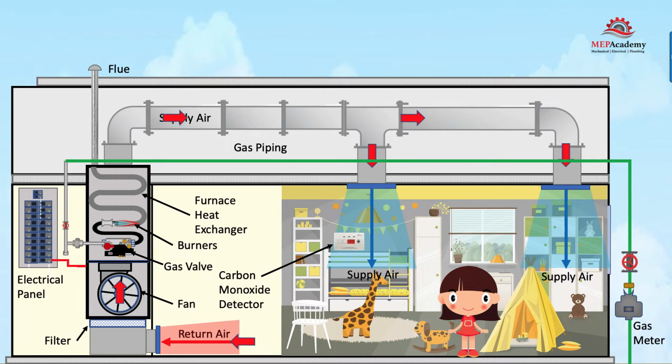This prevents someone from getting injured from a moving fan wheel and motor during service. Filters can be provided on the bottom or side inlet to the fan housing by adding a filter rack if one isn't provided. Remember that the furnace should never be run without a clean filter in place.